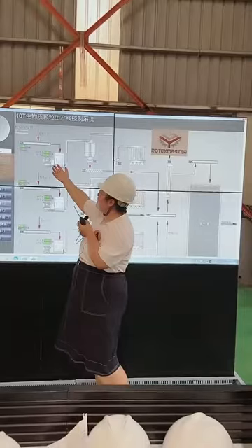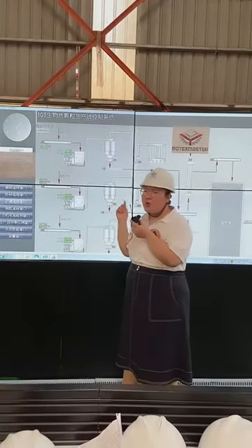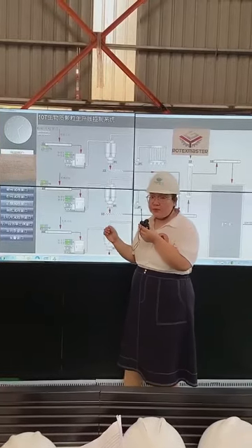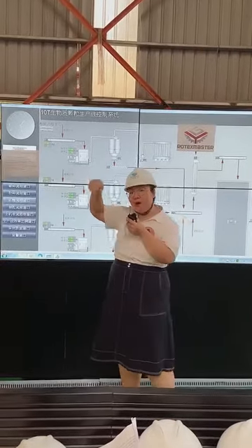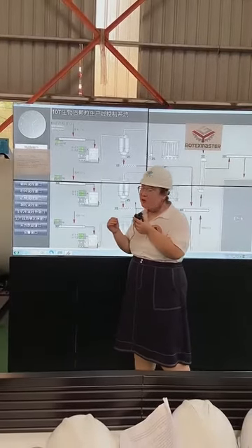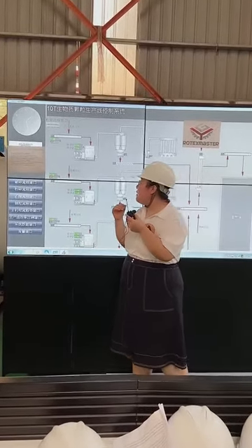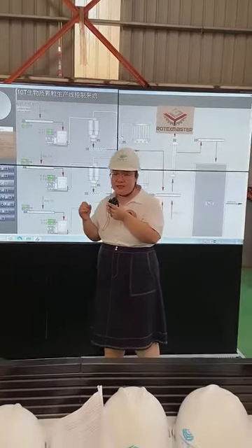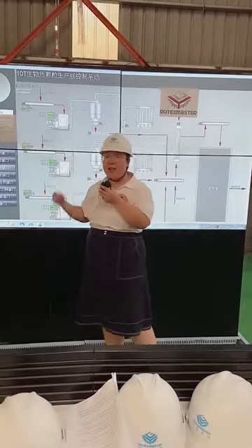For this hammer mill, its rotor can go forward and backward. It will extend the hammer lifetime, and also it will make the machine operation more stable. We advise to change its rotating direction each week.